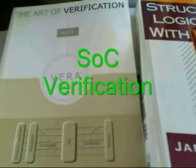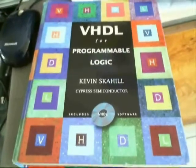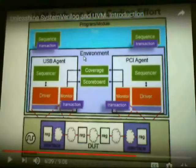ASIC system-on-chip design methodology. Emphasis on functional verification. Functional verification is part of the ASIC design methodology in order to ensure that your design meets functional requirements. The verification process provides for gate-level event simulation, gate-level cycle simulation, gate-level hardware acceleration, and Boolean equivalency checking. Keeping complex verification environments tractable means increasing the level of abstraction with transaction accuracy.